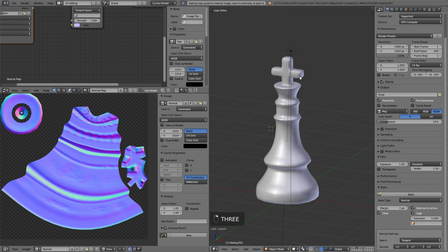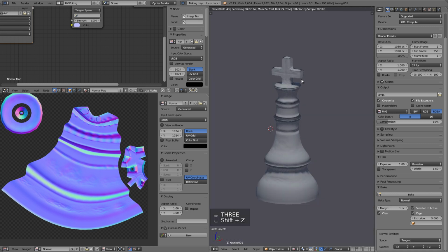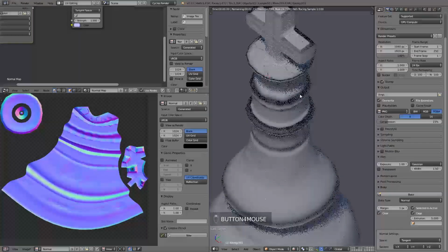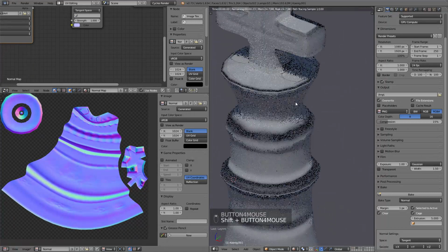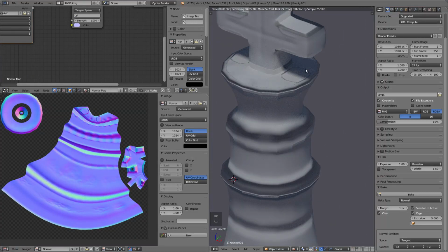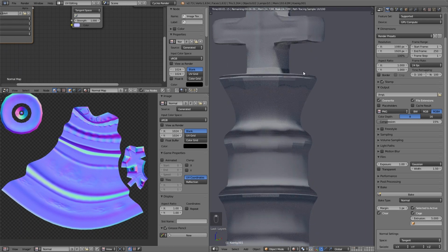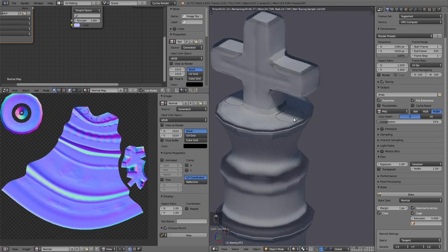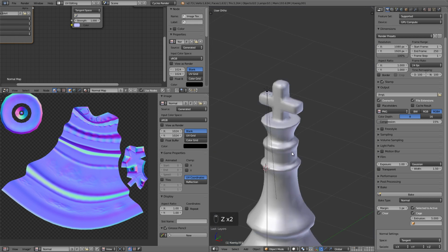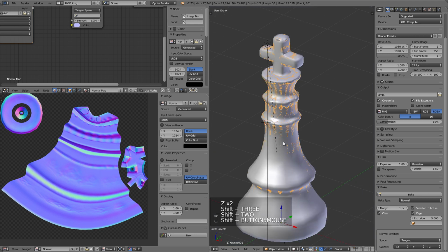This will also be interesting because now there should still be errors. When you look closely around the crown, you see that the parts of the cross are actually creating dents inside the crown here. That is because our cage object has become too big. You should simply set this extrusion level to something between this part of the crown.